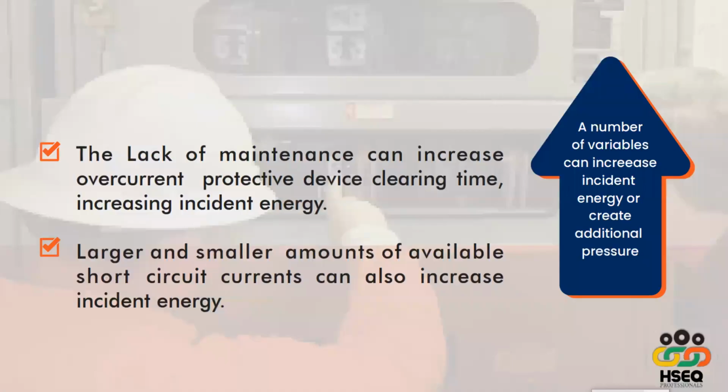So also we have seen that lack of maintenance can increase our overcurrent protective device clearance time. The larger and smaller amount of available short circuit current can also increase the incident energy. So these are the factors which we need to take into consideration.